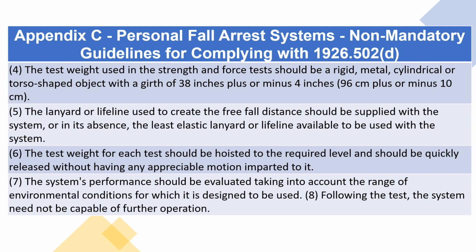6. The test weight for each test should be hoisted to the required level and should be quickly released without having any appreciable motion imparted to it. 7. The system's performance should be evaluated taking into account the range of environmental conditions for which it is designed to be used. 8. Following the test, the system need not be capable of further operation.